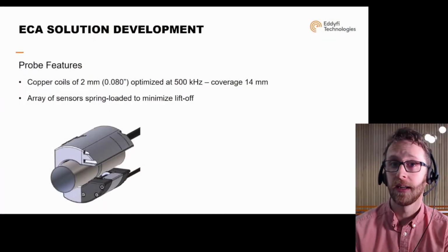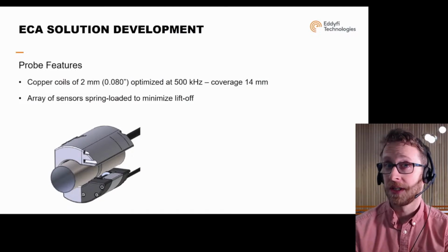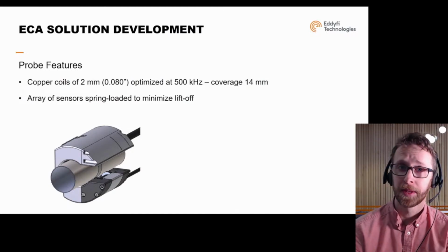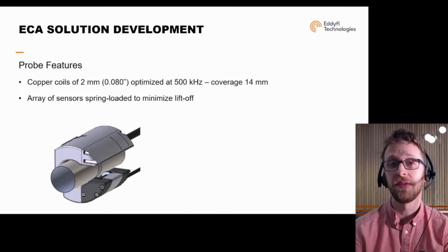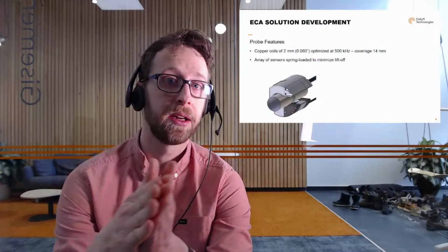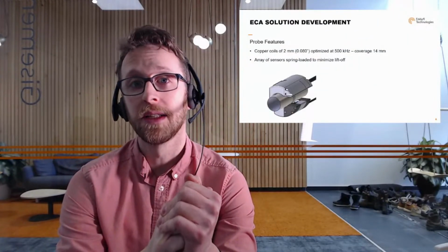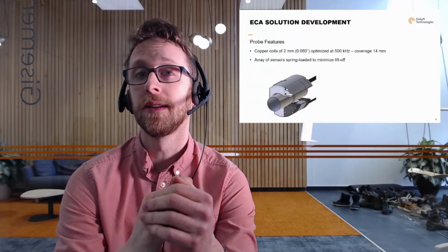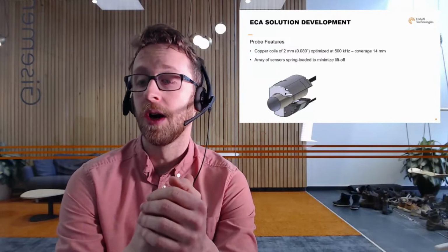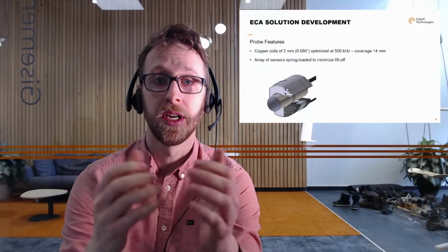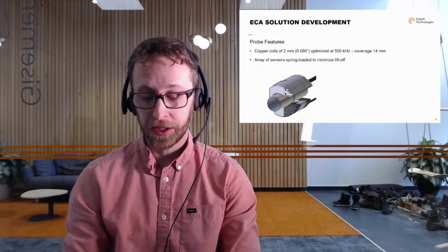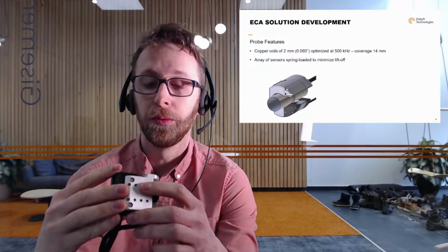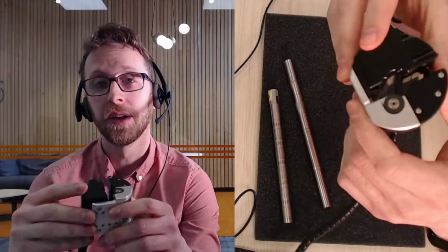is the 1/8 of an inch probe, which, because it is such a small diameter, since we're using a transmit receive topology, the angle between the transmitting coil and the receiving coils is too wide if we had to use it on a tube that is 1/8 of an inch in diameter. So this is why for this specific probe, the 1/8 inch, we need to use 1.1 millimeter coils in short double driver also. But this one, and the other ones, are all centered at 500 kilohertz.